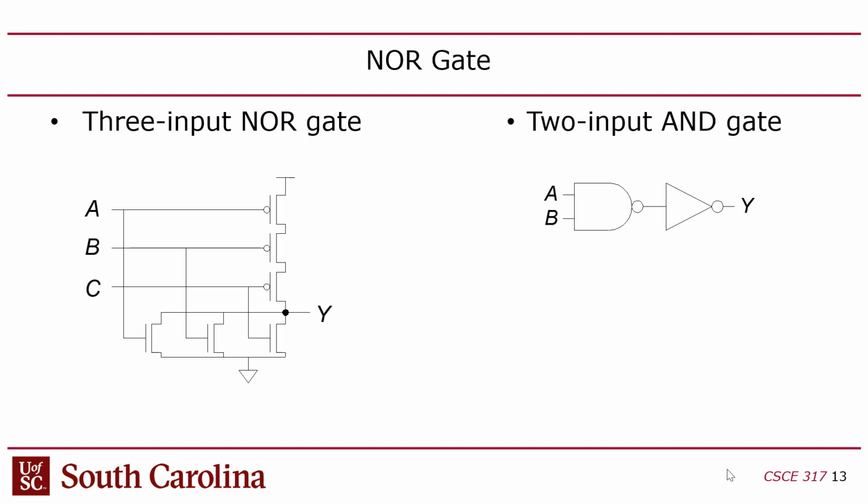So you might say, okay, what's your point? My point is that when you're measuring the gate voltage, it's gate to source, right? You want it to be relative to ground because that would make things a lot easier to understand, but it's not ground. It's the source. Well, what's the source? It just so happens in this case the source is connected to ground, right? So that's nice. The problem is that's just for these guys. When you look at the PMOS, it's reversed. So the gate is relative to the source. In this case, the source is VDD, right?